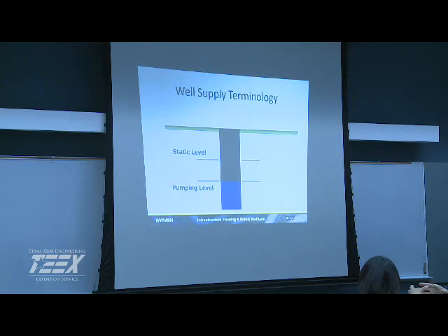So what happens if our water overflows the casing? It comes up out of the top. We have a well like 250 feet deep, but even if we do not pump, the water overflows the casing. Oh, then you're probably in an artesian well. You're under pressure. That's why it's flowing up out of there for you. So we just keep on pumping. Do you have a check valve on the discharge side of your pump? No, we're not using the well right now, but it keeps on overflowing. So when it's not running, it's still flowing?